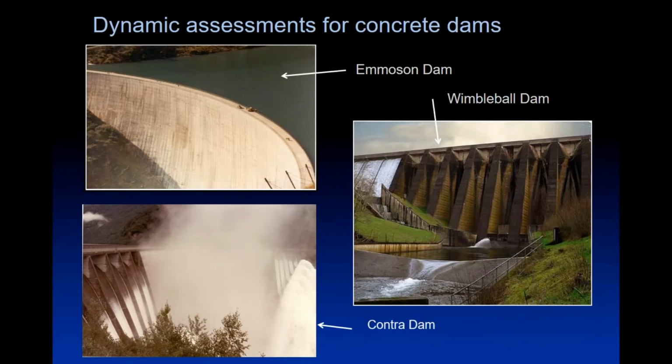Dams, some of the structures that we've tested here, Emerson, top left in Switzerland, is 200 meters tall, and it's 2,000 meters up in the Alps. This was the very first time that we had shaken a full-scale dam of this size and calibrated what the normal modes of vibration are for such a structure.